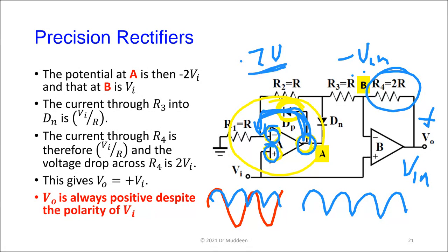The op amp automatically adjusts because of its behavior to make that diode turn on. All you have done at the input is put in a small input voltage, far less than 0.7. The op amp turns on, and to force the non-inverting and inverting inputs to be equal, it will automatically, because of the design of the electronics, put the 0.7 volts on the diode to turn it on. That is what the feedback is about.